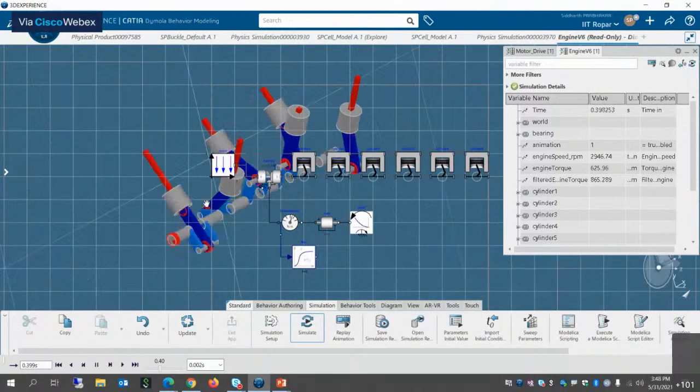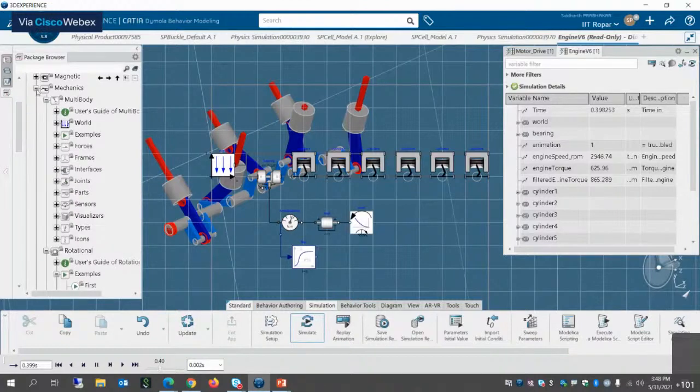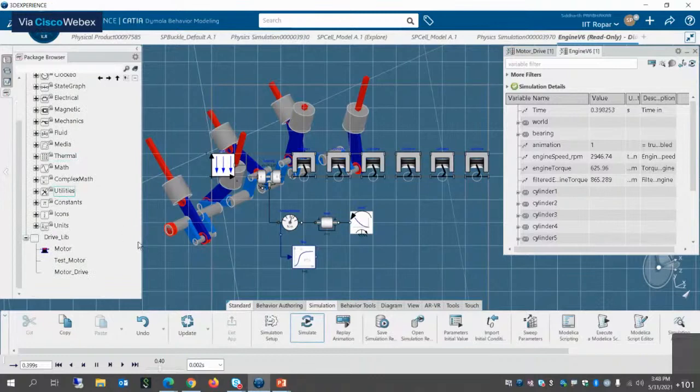So there's a lot you can do with these components and from the libraries that you have, the standard Modelica library. There's only one more example that we're going to try now, which is to build a fluid circuit. So I'll quickly show you how to do that too. Before that, what the Modelica fluid library helps in doing is building one-dimensional fluid circuits. You can drag and drop components from the fluid libraries in order to build these fluid circuits. The media library is present from where you can define the mediums, or you can define your own medium properties if you have the fluid properties that you want to define.